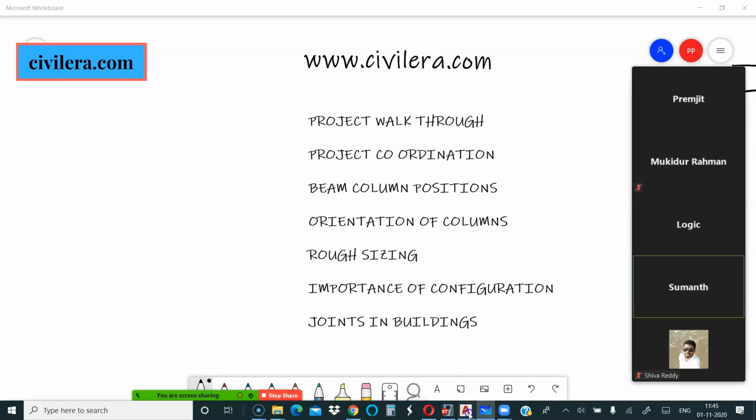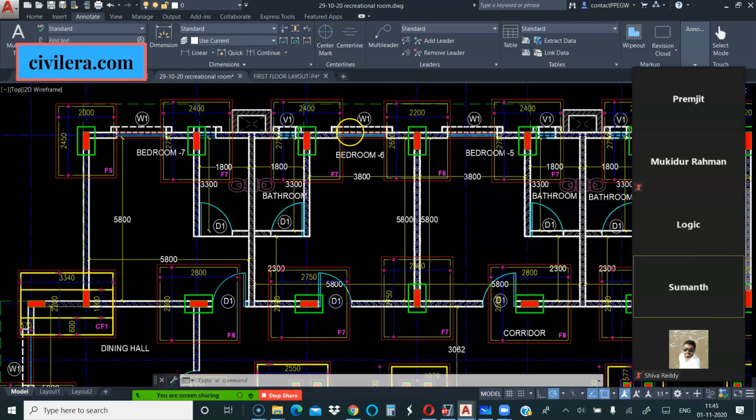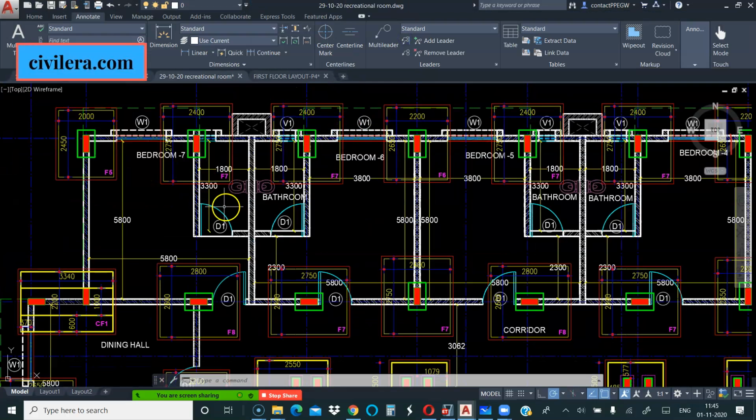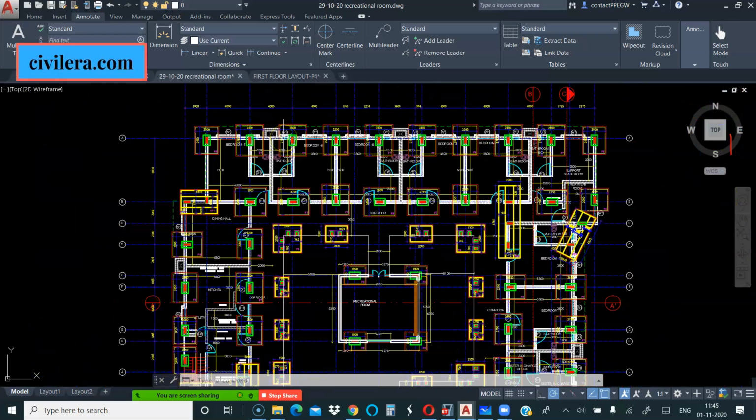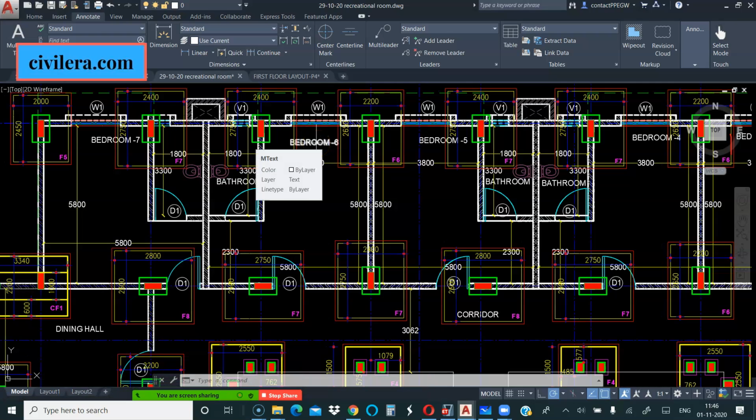Many times what I do is, if the architect is hesitant to give me the load, or he says, okay, I don't know the wall positions, it may keep on changing, in such cases I make a load diagram. Or sometimes it's an office building and he says, I might have partition walls everywhere. Then I will sketch on my own and say, this is the intensity of wall that I have taken. You can have this anywhere in the floor, but not more than this length. So I will give a total length and the thickness. You cannot exceed this in this particular space. If you exceed, my design will change.